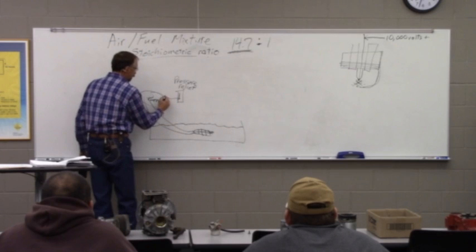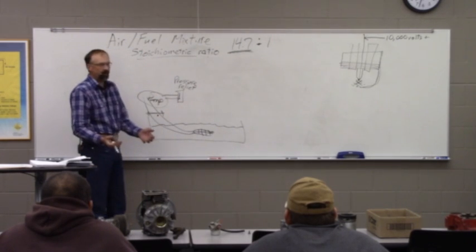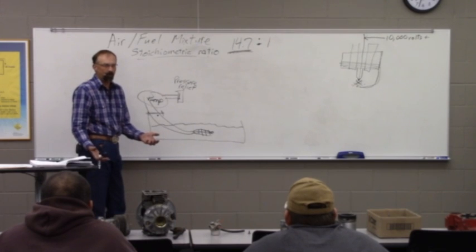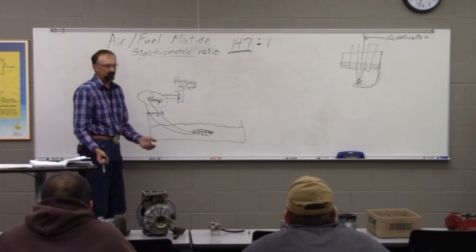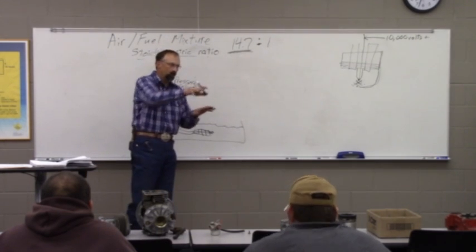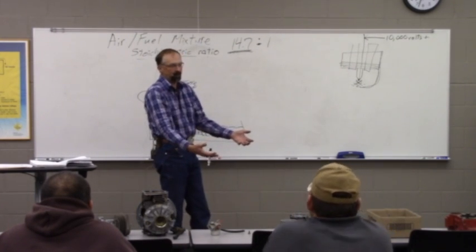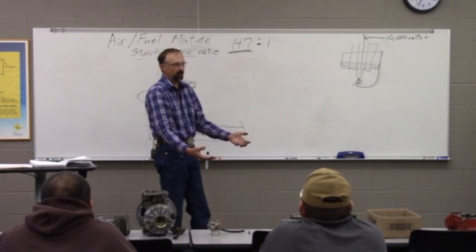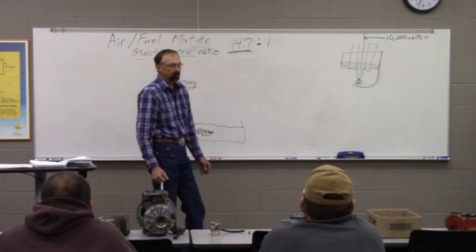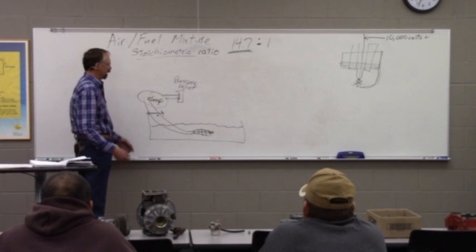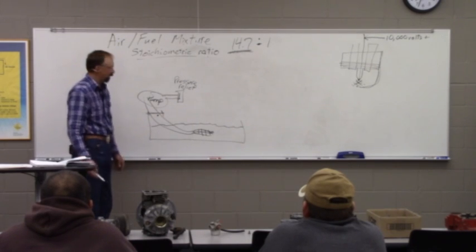The pressure relief valve does just what it's talking about, because engine oil or any oil changes thickness a lot based on temperature. Engine oil at 30 degrees is way thicker and way harder to push into our different bearings, and likewise escapes out of our different bearings way slower than oil that's at 200 degrees. So this pressure relief valve is especially important until the oil gets warmed up to normal operating temperature.